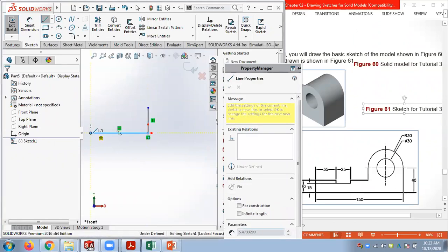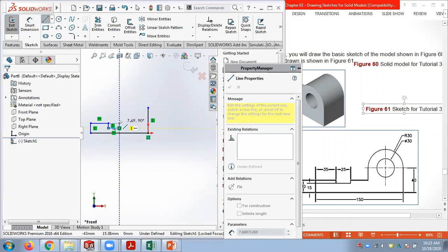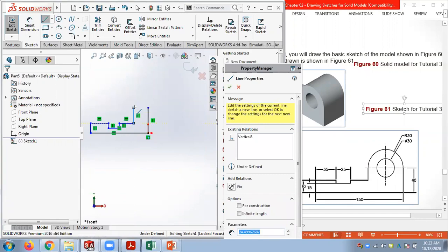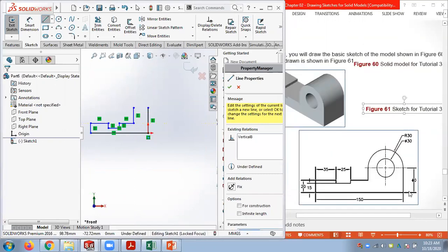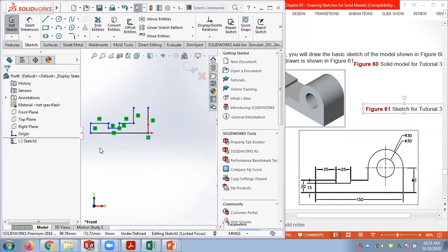So I'm trying to get the origin into my drawing, then it's easy for me to make the drawing fully defined. So that's what I'm thinking. Something like this. So I hope you understood. This is the origin location in my drawing. So I'm trying to take it into the lines, not to the circles. Then it's easy for me to make it fully defined.